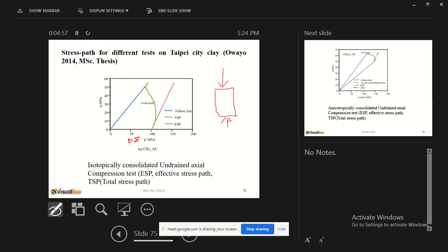All right, axial compression. But there can also be axial extension, where the sample is increasing, and this is achieved in several ways. If sigma 3 is higher than sigma 1, then you can see this extension can happen, axial extension. So depending on the values of sigma 1 and sigma 3, you can achieve either shortening or extension.